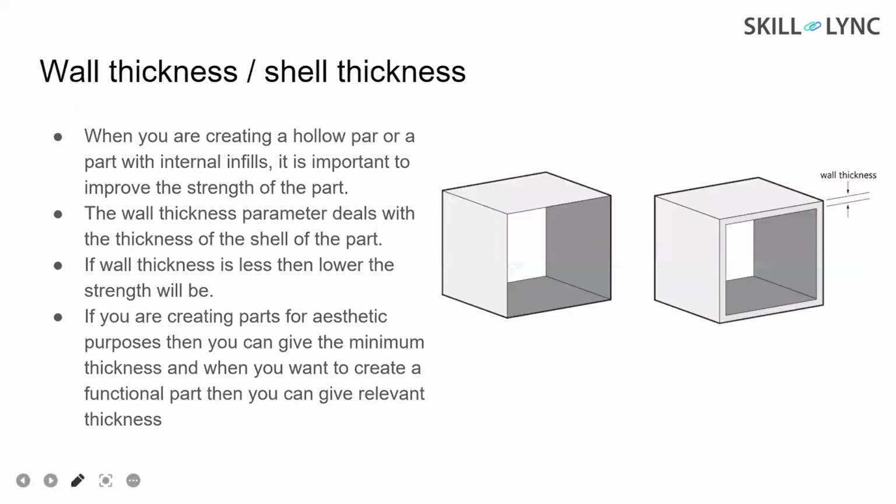So next is your wall thickness. We talked about this wall thickness. When you want to manufacture or 3D print a part like this, it's a shell, a hollow part. If you want to 3D print this part and the shell is very thin, it will fall down, for one thing. But here, I'll give a support so that it will withstand the sagging or falling, or the deformation in our body. But what happens after that? When you are removing the support material itself, because this is very fragile, when you push it, it may break. In this particular case, your model is very weak.